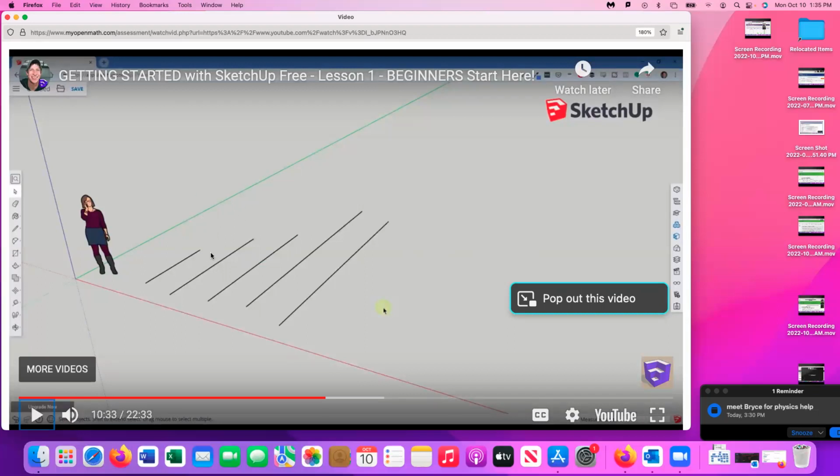Normally, I don't remember what color they are normally, purple or something like this, pinkish purple. But if you drew one that was going downward from this lady model to the right bottom corner of the screen, and if you adjusted it just right, it would highlight red eventually. So that would be parallel to the red. And then if you put it standing up next to this lady over here, you'd get blue eventually if you moved it around and lined it up so it was parallel. So when it is parallel, it does that snapping to the color of the axis.